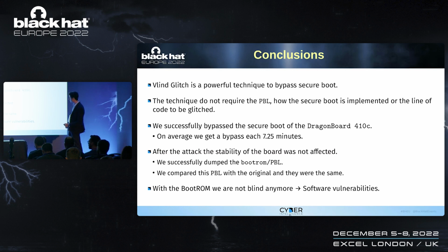So we successfully bypassed the secure boot of this DragonBoard. Basically, as Vicente said, we just modify a Qualcomm signed programmer, resign it with our keys, send it to the board, and eventually we get success. On average, 7.25 minutes, which is a very nice approach. We are usually happy when it takes less than 1 hour, so 7 minutes is super nice.